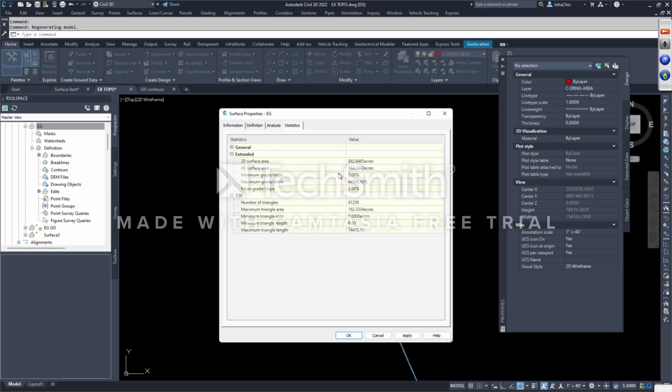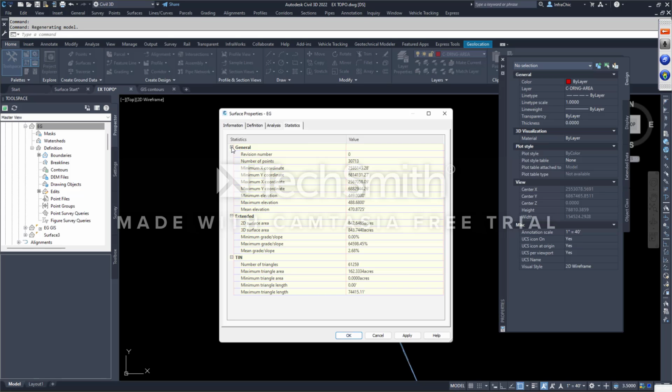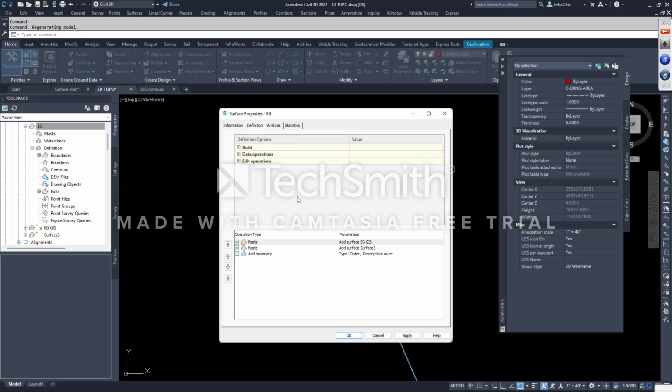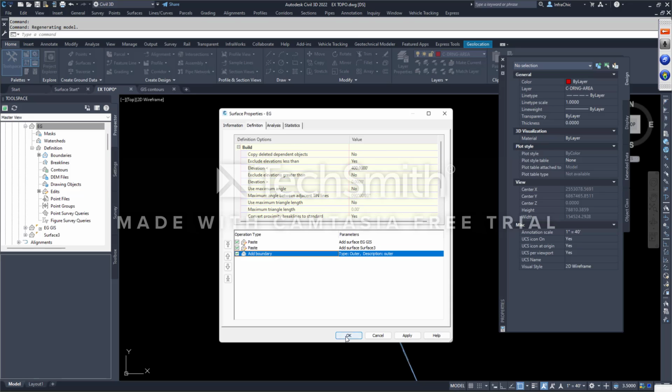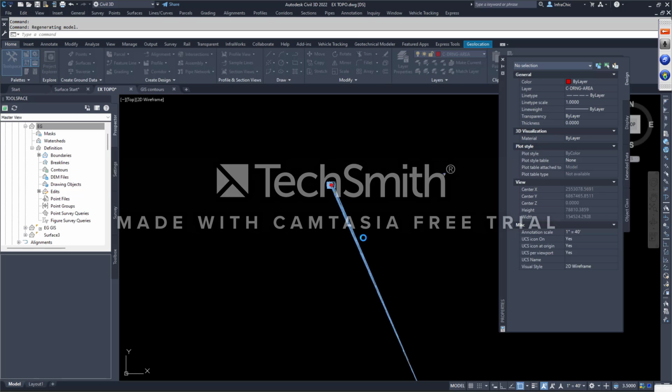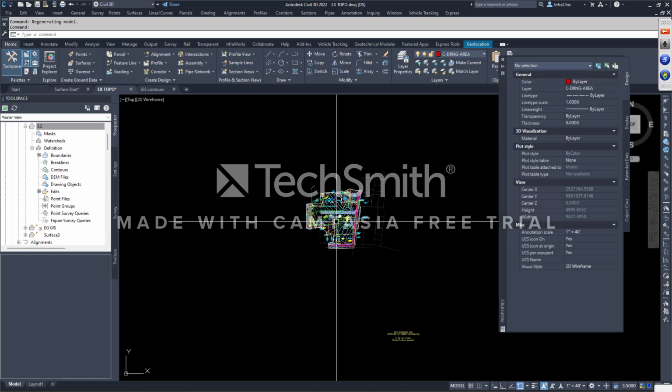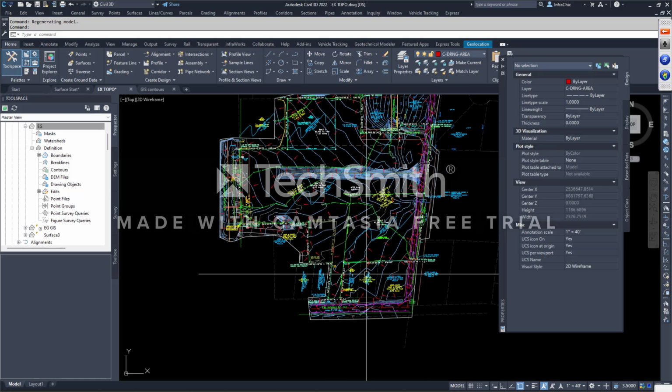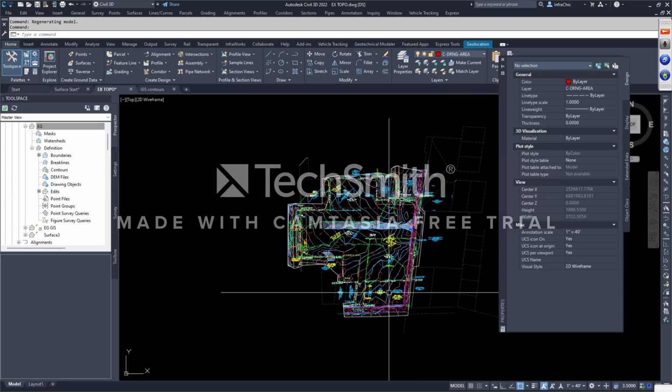Triangle, nope. Extended, 2D, grade, average grade, flat. Nope, minimum, max, and mean. So no, there's no 0. That tells me that I need that boundary of some sort. There's something going on. Even that's got set up to be lower 400. So there's some point randomly that got put into the surface, and God knows what it is. But that shows you what can happen if something's outside of your boundary and it just pulls the living daylights out of it into your stuff.